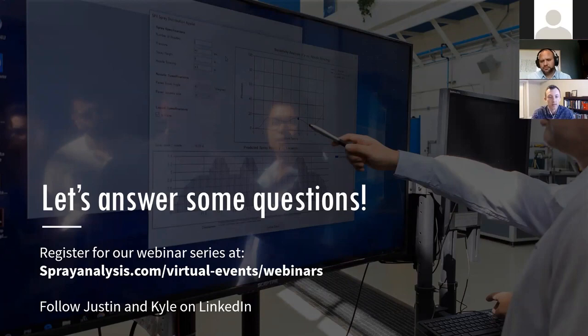So with smaller droplets, the mass to charge ratio, you're going to have a higher charge concentration in small droplets. He said typically if you're looking for a more uniform charge, then you want to go to lower or smaller orifices and smaller droplets, which will tend to compress those parameters together. But if you want more detail on that, certainly reach out to any of us three, and we can get you in contact with Paul or somebody else to have a direct conversation, get some good answers there.